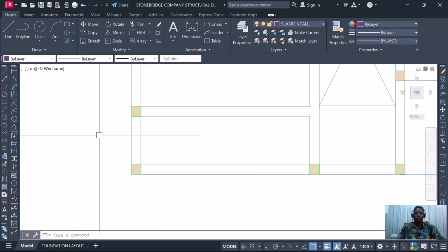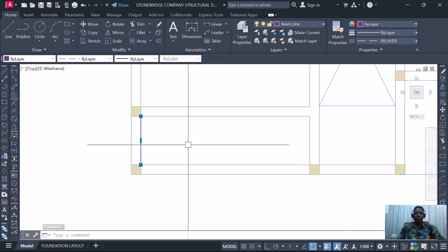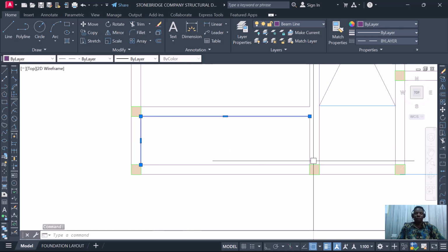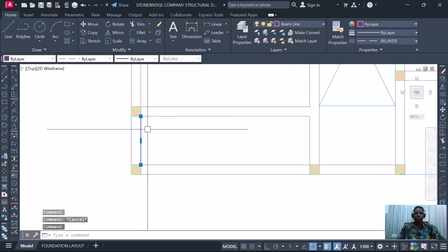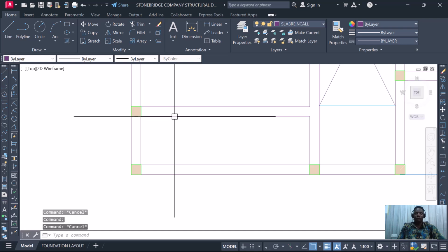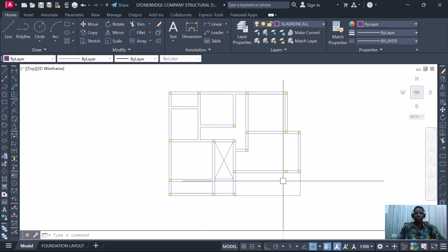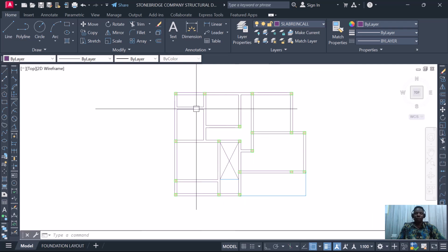So when you're doing a general matting, we have what we call the main and the distribution. When you want to do your matting, the main is the shorter length while the distribution is the longer length. Irrespective of that, let's say we are assuming only this panel that we're going to do. Then this shorter span is going to be our main, and the longer span that is along this line is going to be our distribution, meaning that we're going to lay this on site first before we cross it with this. Which means this will be at the bottom, and this will be at the top, which means this is going to be crossing this, for the mat.